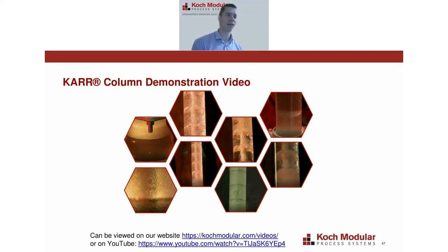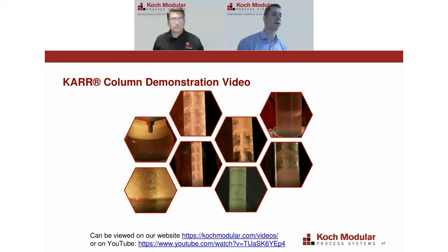If anyone has time and they're more interested in pilot testing and some of the other things I discussed, there's a video that you can find, like most other videos, on YouTube, a 10-minute video of just the pilot Karr column, and it goes through a lot of the things I discussed earlier that we see when we pilot test, like the impacts of wetting characteristics, coalescing, emulsion bands, and flooding. So if you have some time and you're interested, I think this is really worth a watch. And there will be a link to this included in the presentation.